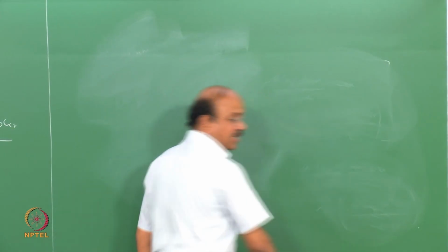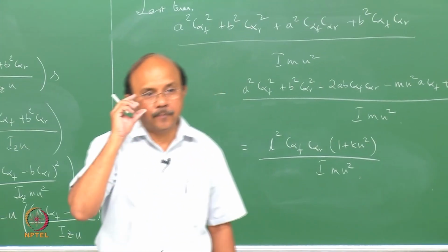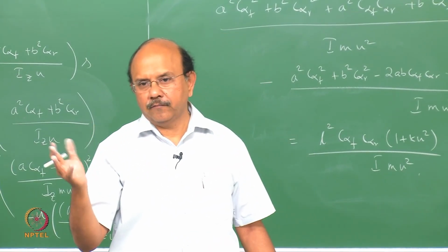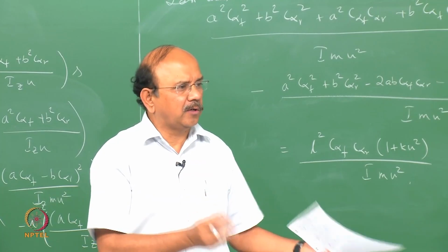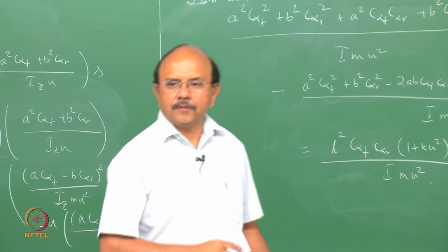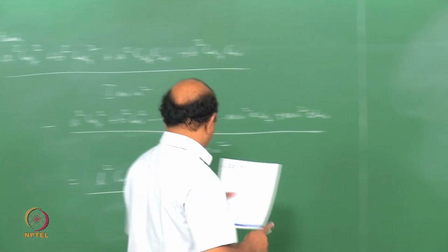Then we take the second term and I'm going to simplify it. Remember, what is my goal? My goal is to find out ultimately omega n and zeta. I want to find out the poles. From poles I can find out, or I'm going to develop a much simpler technique in order to find out the natural frequency and the damping ratio. Okay? Right? So the second term